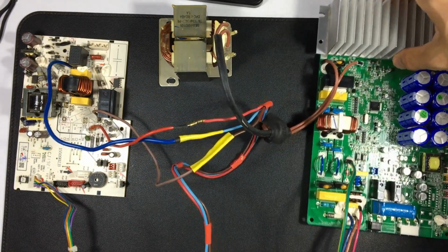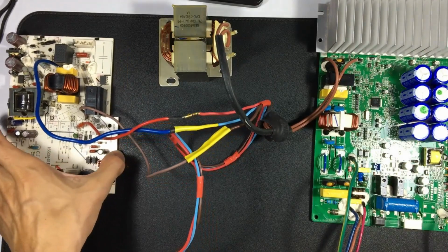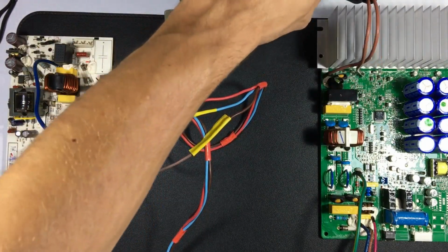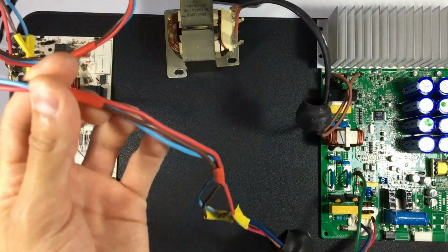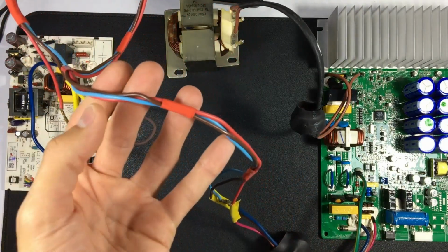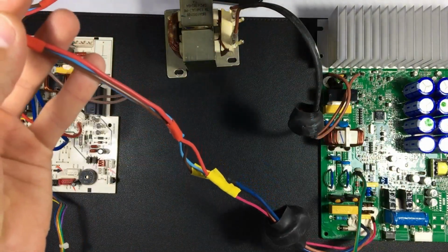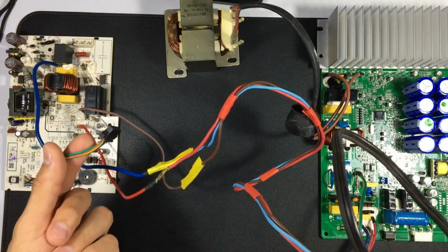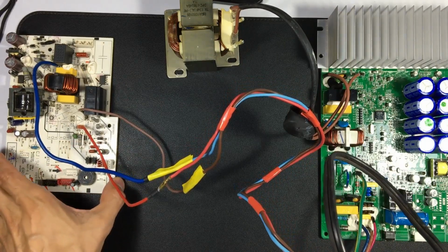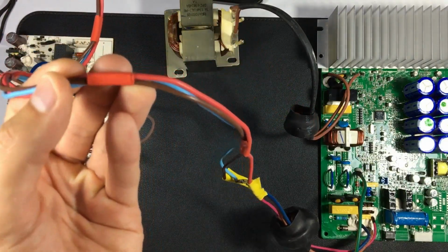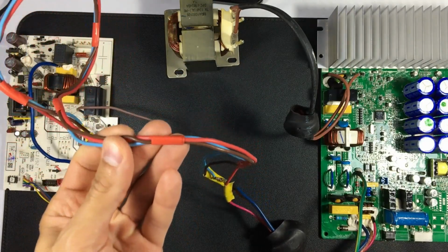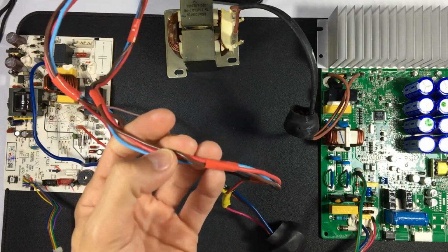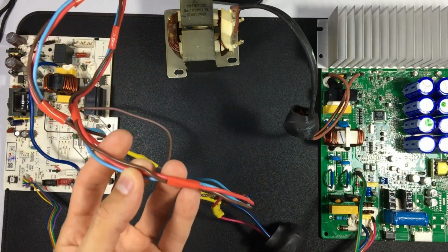As a sample, to be able to explain and understand it, we have an indoor and an outdoor board with its reactor, which it needs to be able to turn on and energize. Here we have the electrical interconnection: line, neutral, and signal. They are the only three cables we have. We don't have the earth connected so as not to confuse us, nor do we even have the display connected. To understand how this works, first we are going to do some measurements and then we will explain in graphs how it works and how it communicates from one side to the other.